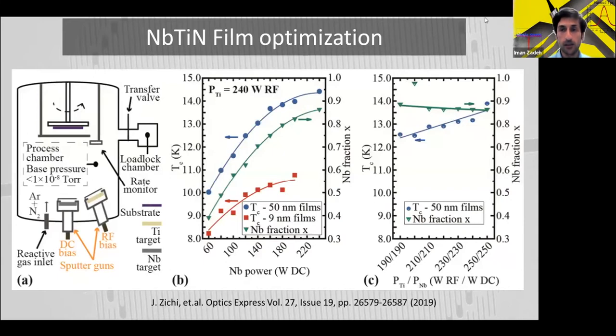It's built upon earlier work of last year, where we used this co-sputtering system. It's a magnetron sputter. We sweep the parameters of the superconducting material. So in this case, mostly this is the niobium content. And for every wavelength, every application, one needs to do this sweep separately.